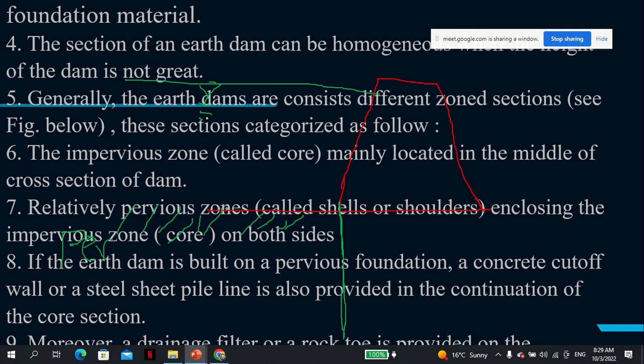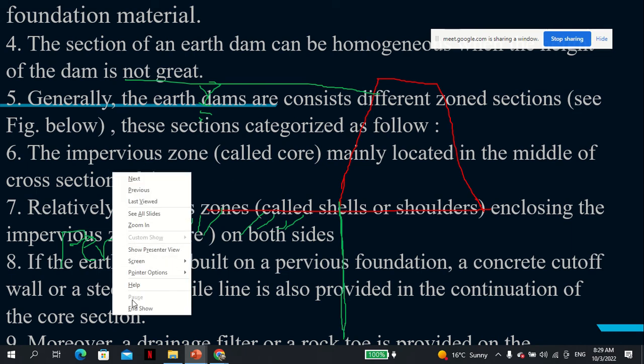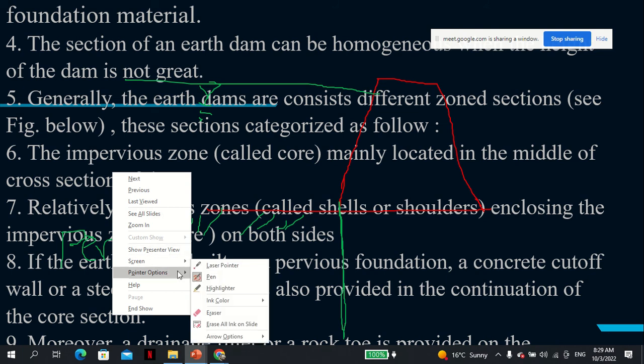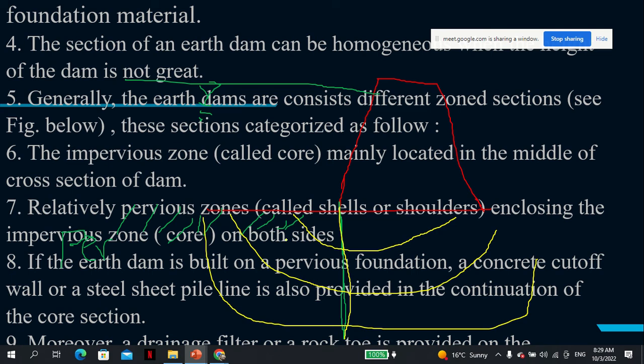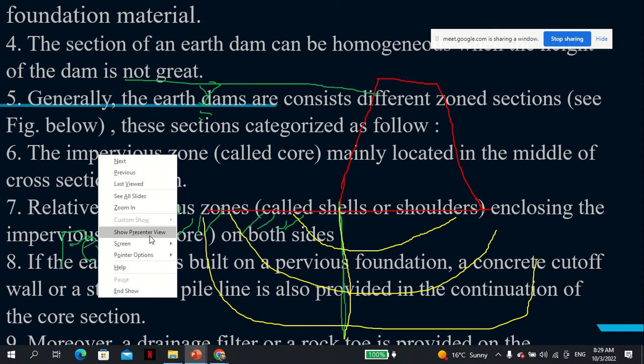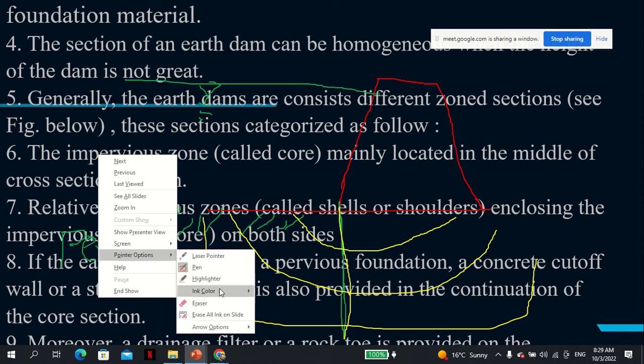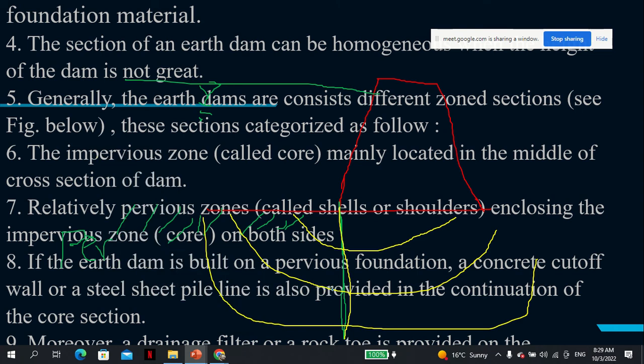because the disaster would be the water here would want to flow there, there, there, if the sheet pile is not there. But once you do the sheet pile, then the water, let me use a different color. Then the water, if it has to flow there, it increases the flow path, and therefore the seepage would be much less and the dam would be safer.